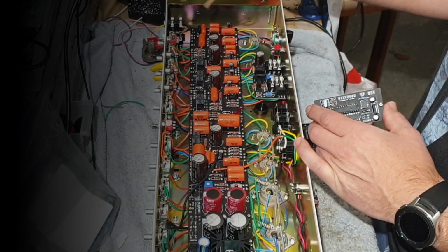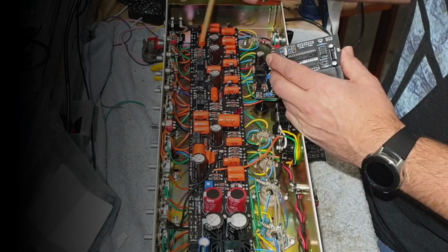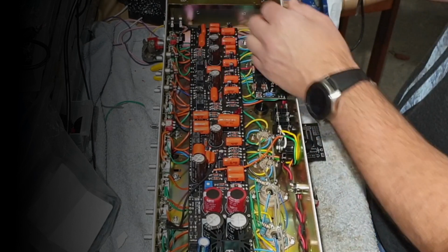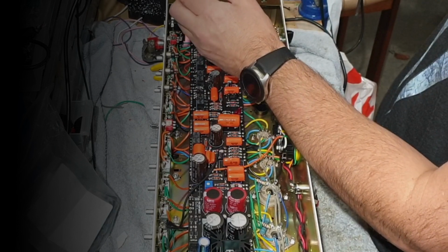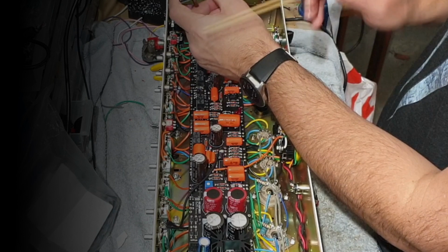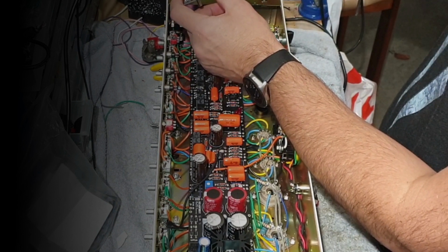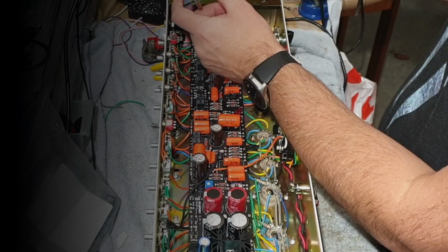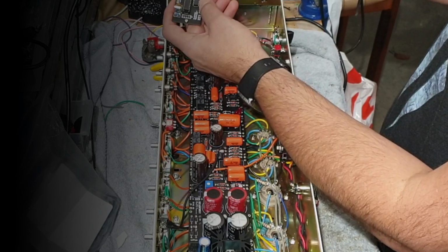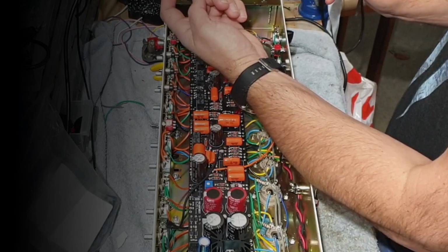So what we're going to do is still tap off the 12-volt DC line and run it to the MIDI board. The MIDI board has its own voltage regulator. This is a 7805 regulator, so I'm going to use this to knock down the 12-volt DC supply to a nice steady 5-volt DC, which can be used by the chips on the board.